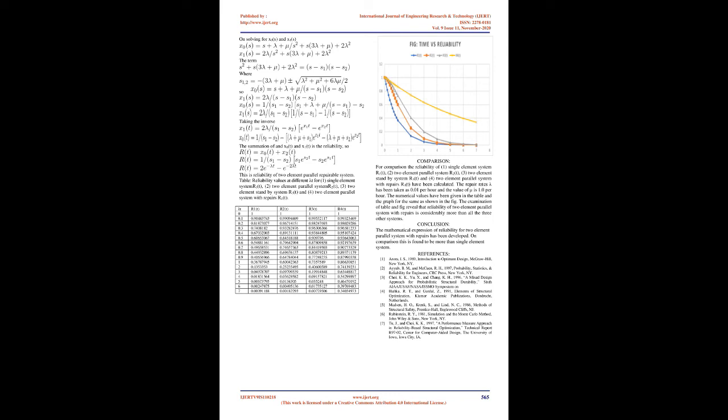D. Duration of a single downtime. It is based on the time taken to restore a failed product or system to its working state. The duration of a single downtime in such cases should always be less than a certain critical time. Example: the failed duration of an ambulance transferring a critically ill patient should be less than a certain minimum period. Another example is a scanning radar system. The longest duration of a single downtime should be less than the time the enemy's fastest missiles take to reach the destination. For the reliable design of a product, any one of the above criteria, or more than one in any combination, may be used depending on the type of service expected from the product.